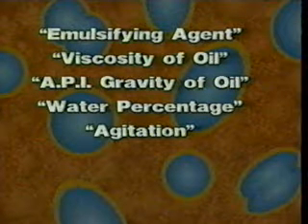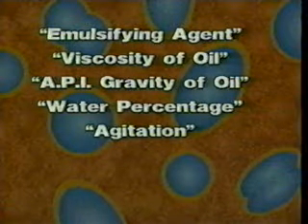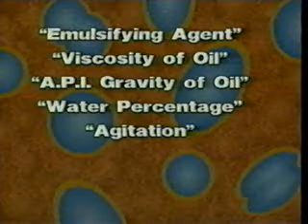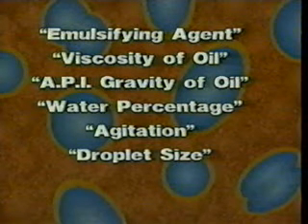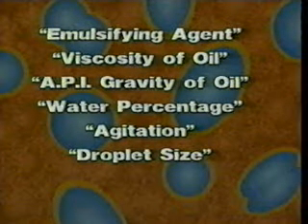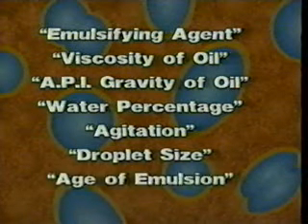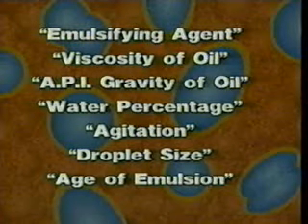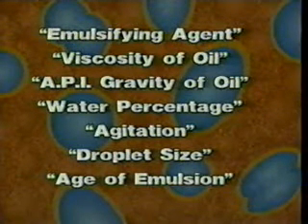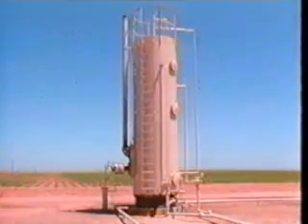Increased agitation causes greater dispersion of the water droplets, thus increasing emulsion stability. Small water droplets give more stability to the emulsion since they're lighter and don't settle out as readily. Old emulsions die hard. The longer an emulsion remains untreated, the more difficult it is to break.